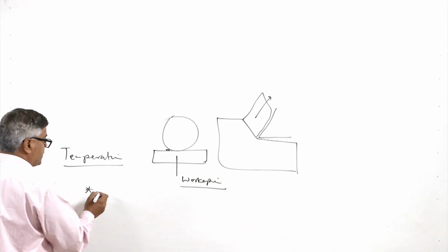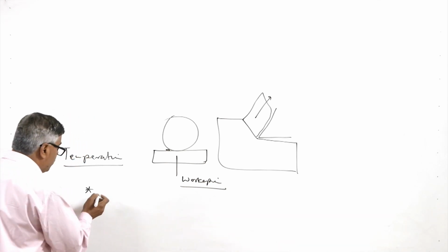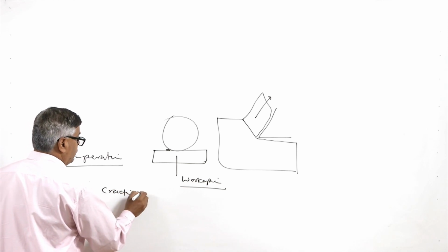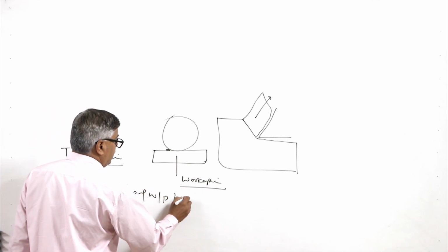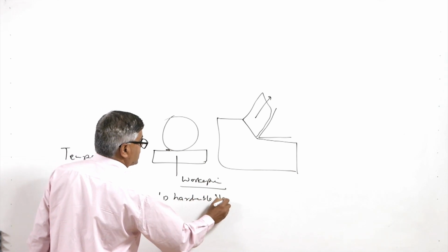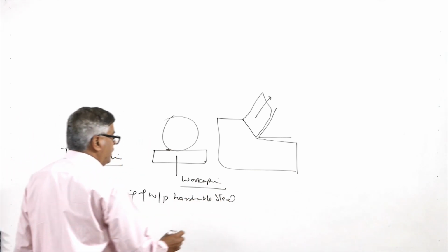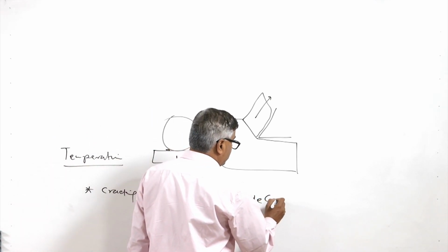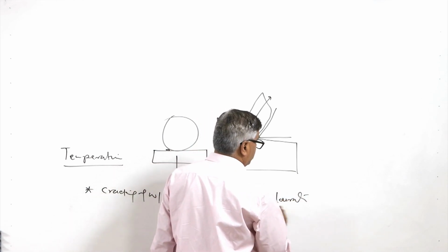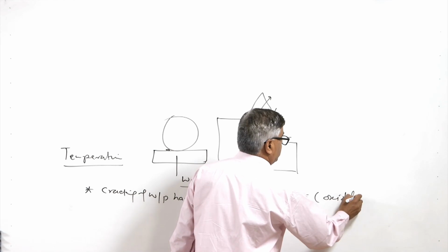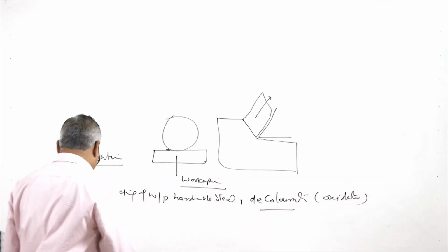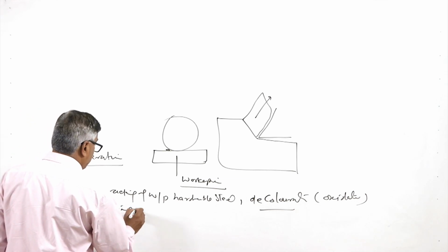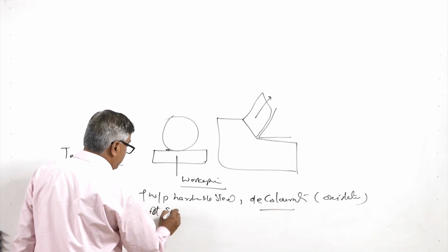These effects appear in different forms, such as cracking of the workpiece, which hardenable steels experience. Apart from this, there can be oxidation, which can lead to discoloration of the surface due to oxidation of the heated metal. There is one more, which is called burning of the material, like formation of hard spots.